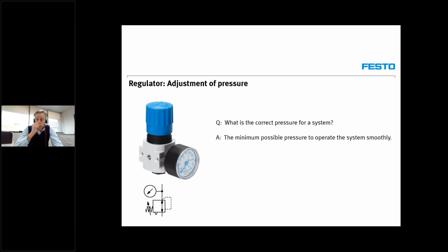In our energy saving course, it's quite interesting to see exactly how much energy and money is wasted by operating an actuator at a higher pressure than what is necessary. Now, this is by far the easiest and cheapest way to save money. It's just to check what your operation pressure should be and set your pressure according to that.